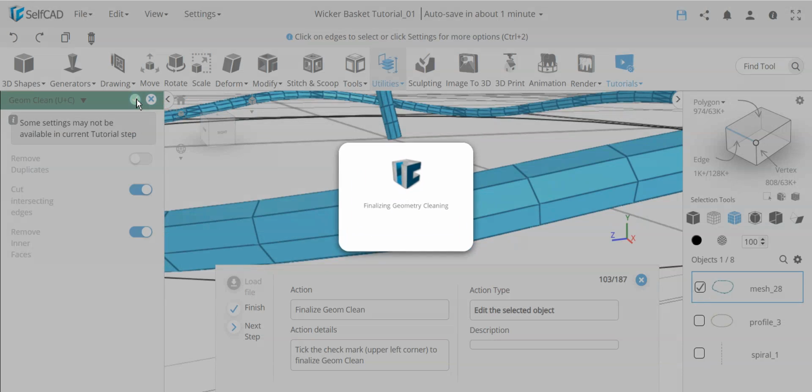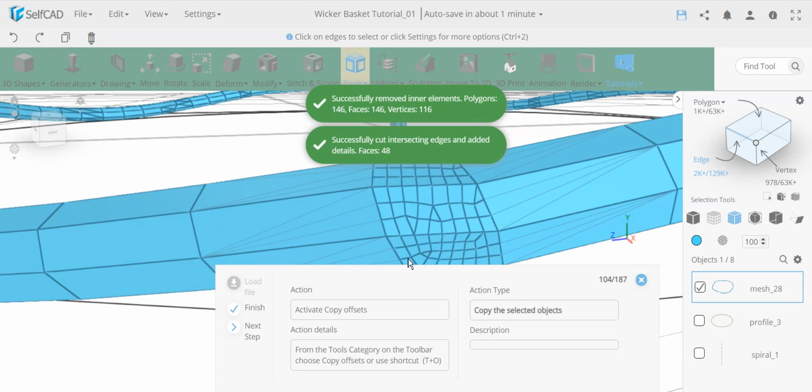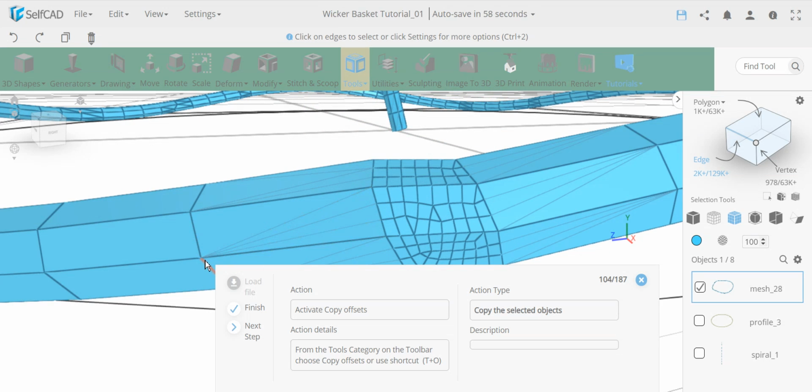And if you click over here, look what's happening. This actually created these cuts. You can see the way it connected it. It found the vertex over here and far away, and it made all of these edges here to actually connect them, same all of them, and this is how this becomes manifold. This object is now manifold.